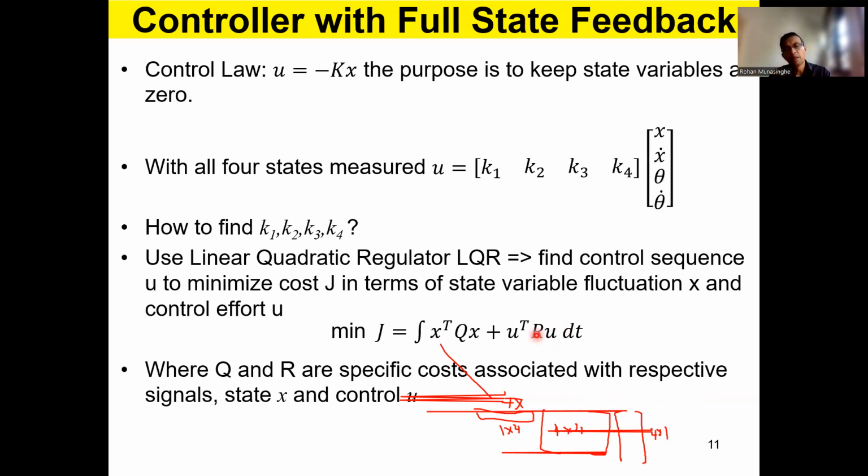By adjusting Q and R accordingly, you can get the total cost: your effort, and how the state variables change before they stabilize. You can have huge variations before stabilization or maybe small variation before stabilization. The latter one is probably low cost, whereas the former one is high cost.